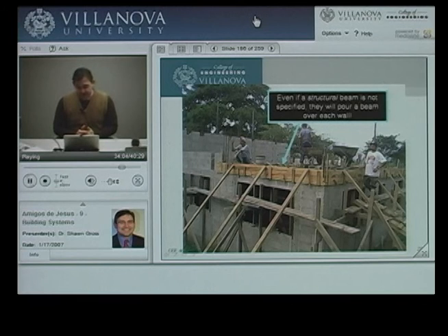So you will see a lot of what we call a double beam type system, where I might have right over the window a beam at this level here, and then another beam a little bit higher. In this case, it's up about here, where that beam will look like. And then, of course, my columns coming down here and there. You'll see that in many of the typical photos from the site, as well as probably in your architectural drawings. It's a pretty typical way of doing things on the site.